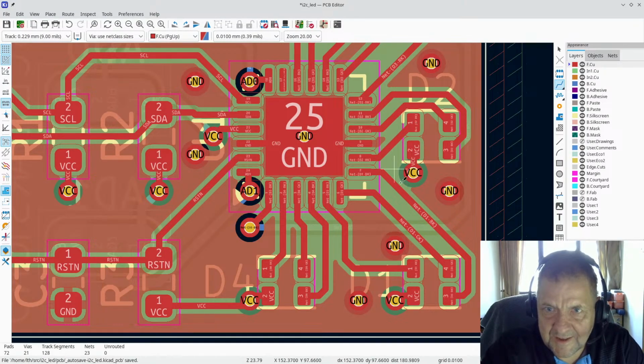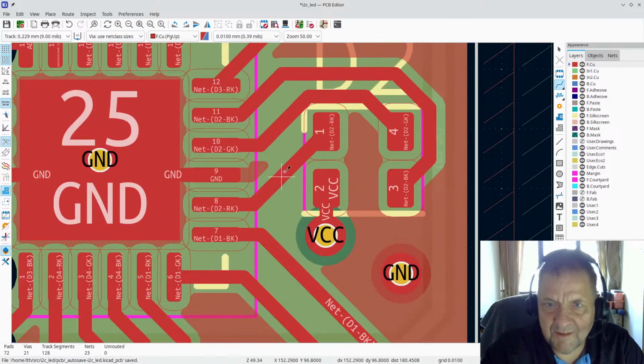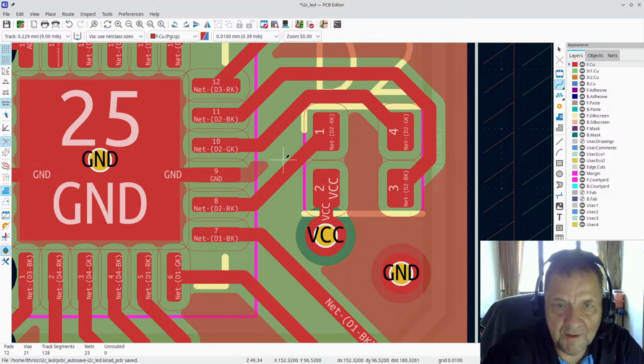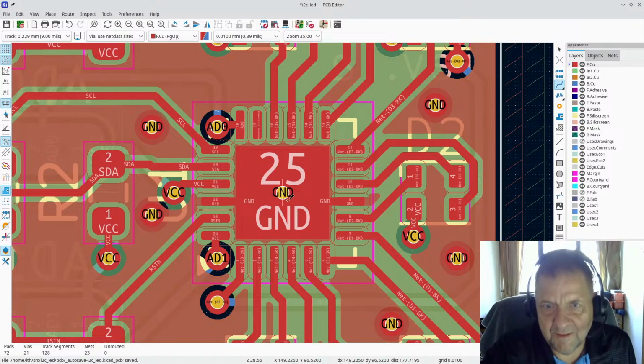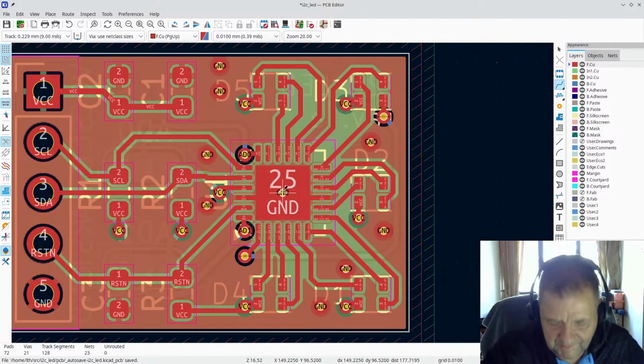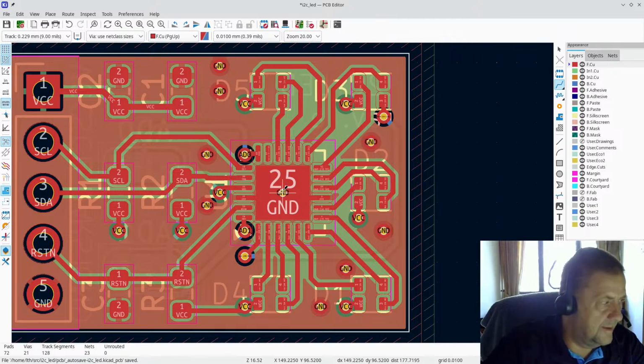Because it gets a little busy over here because of that LED, I can't really squeeze a ground wire in over here. I could probably, but I won't. That means that the only ground is that little skinny one that comes down here, and I like a little more ground, so why not put a ground in the center that will then connect to the ground pin. It just makes it better grounded, that is all, and that is a pretty important thing.